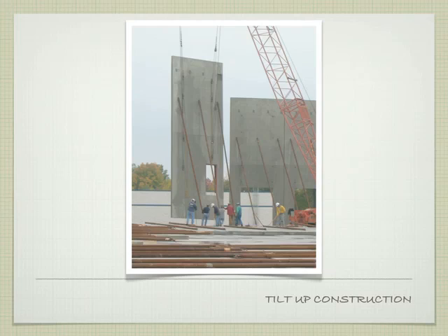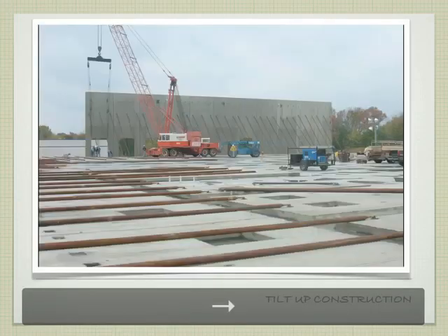That's the challenge. So you have to think of that as you're now lifting up the slab, so it's going to have a tendency to bend, right, against the lift points. So you have to do reinforcing on the bottom at midspan and at the top, right, just like we would do in a building, even though ultimately it doesn't matter because it's all vertical, right? So you end up with extra reinforcing to accommodate that lifting, right? So you're on the right track there, right?